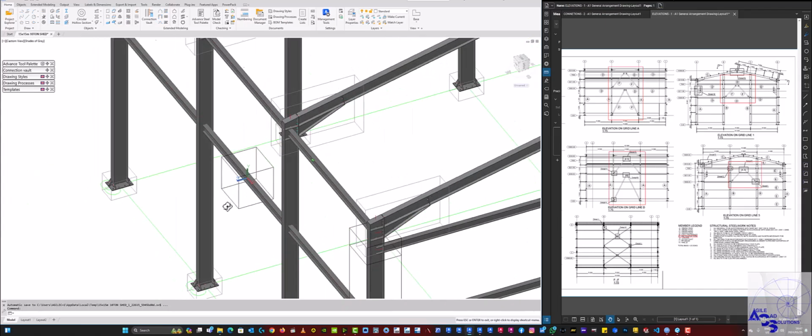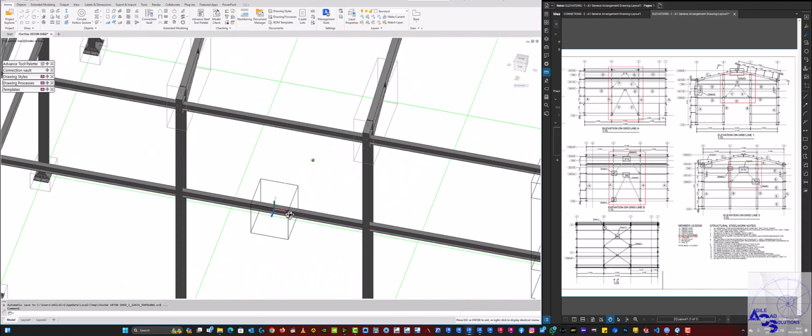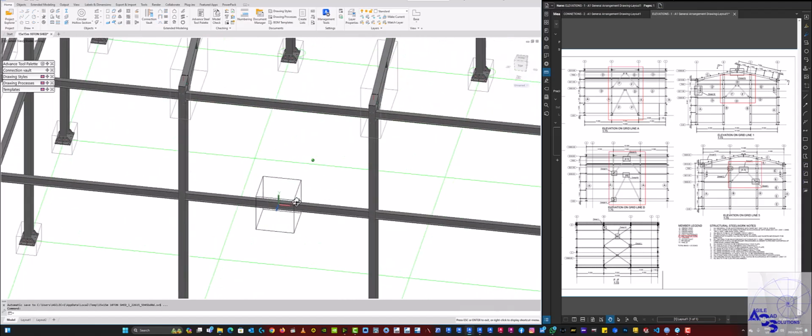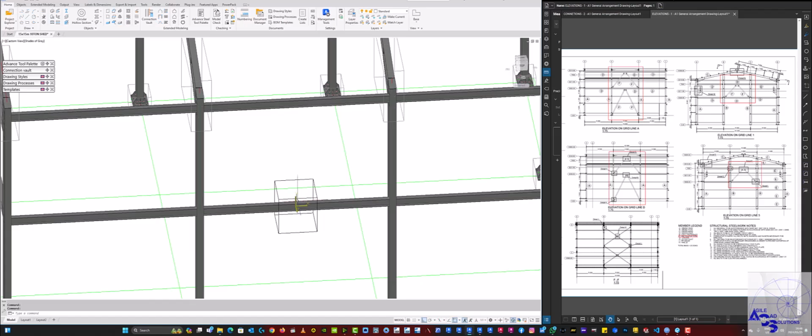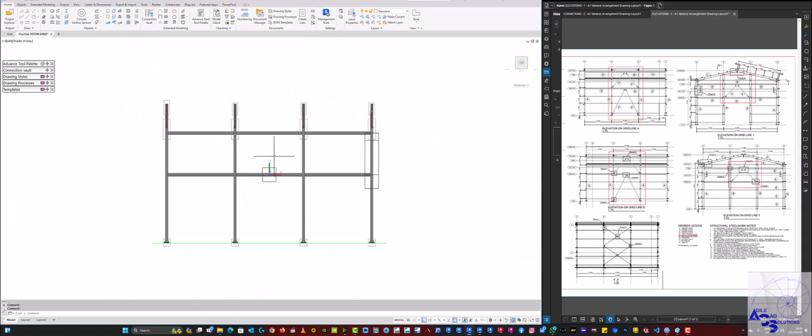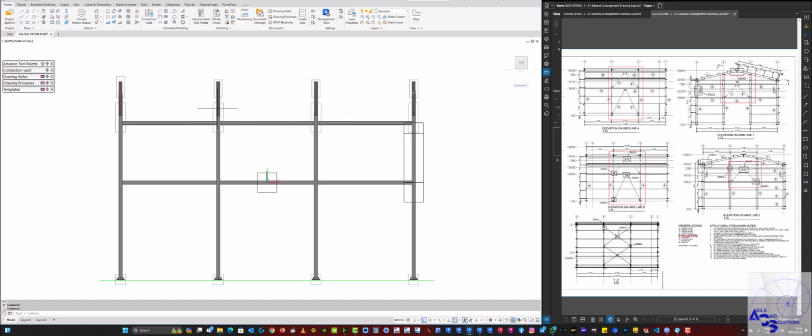All right. Now, as you can see, it has been created centrally to the elevation or to the point where our UCS is. So now we want to see only elements about this middle bay where we are going to add our bracing. So what do you do? Select the box and then click the node and drag the node to the side.